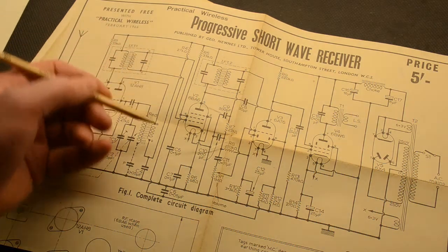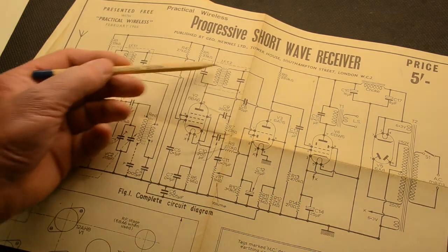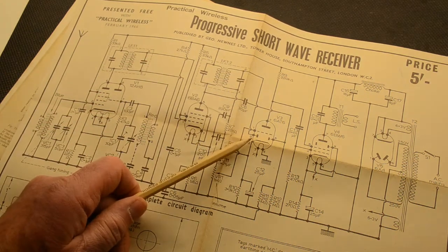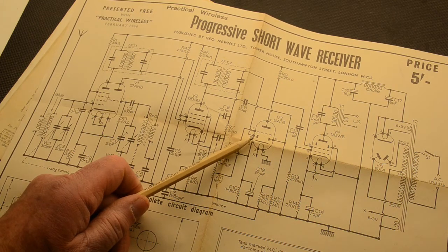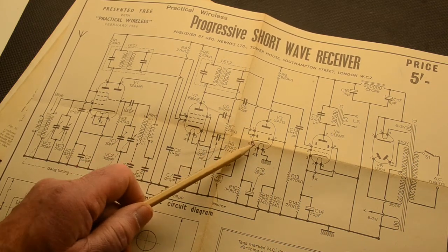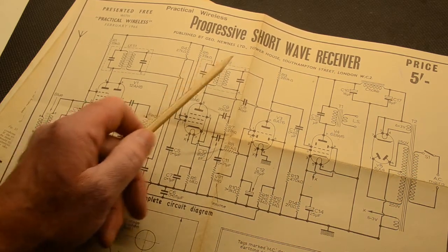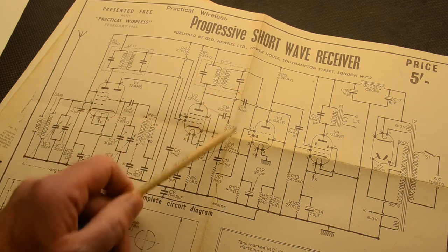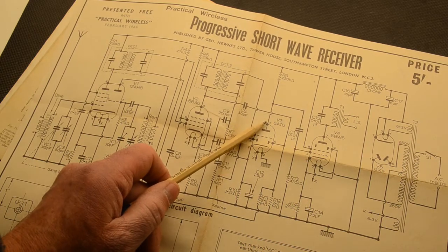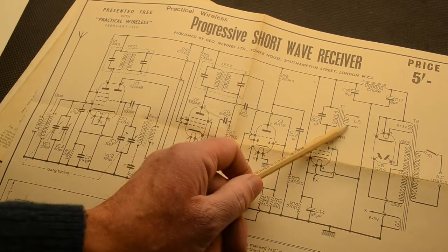It goes through. In this circuit we only have 1 IF amplifier, because once it goes through the second one, this is tuned to 465 kilohertz, it comes out and it goes into here. This is called a double diode triode. It's a triode valve, with 3 electrodes, grid, anode and cathode, plus a filament, and it has 2 diodes built in. So what we're doing is feeding the modulated 465 kilohertz signal into one of those diodes. If we look on the anode here, we find that audio comes out. The audio is then fed into the output valve and from there to the speaker.